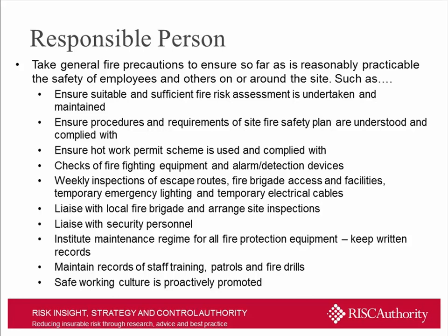Some again more important than others. Ensuring that a suitable and sufficient fire risk assessment is undertaken and maintained. Again, a fire risk assessment is a snapshot in time, but the legislation requires you to ensure that it remains suitable and sufficient. And so when you've got an ever-changing premises, such as you're going to have in a construction environment, you need to make sure that it's regularly updated and that whatever precautions are required at the time and looking forward are being suitably addressed.